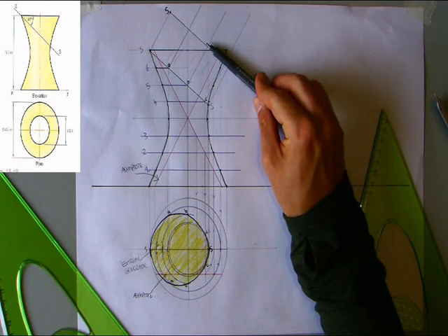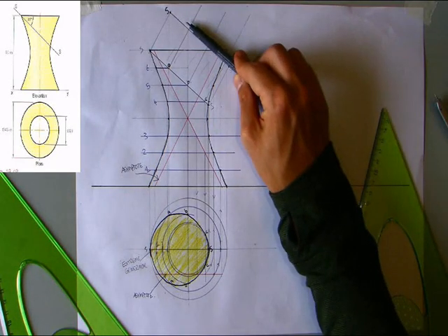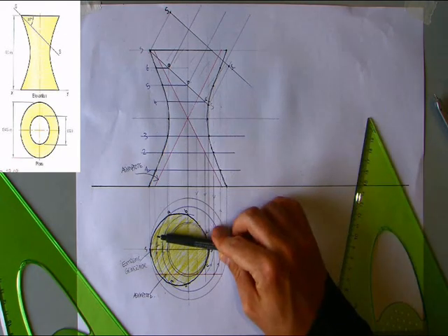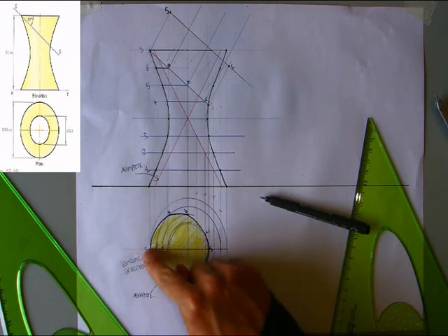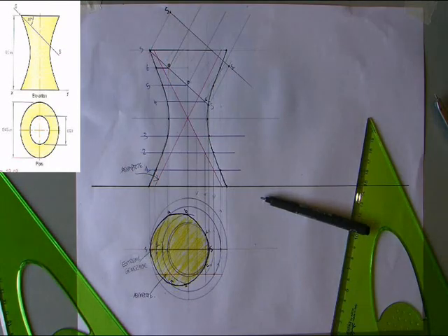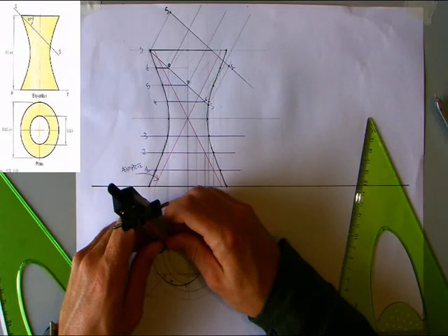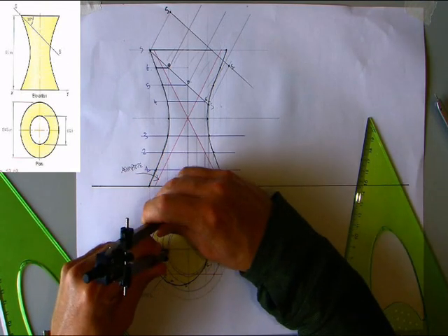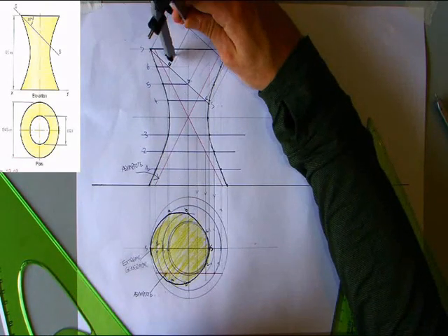So, to get our measurements for this true shape, we're going to go back 2 views, and that means this is an auxiliary view, so we're creating that drawing from here. That's back 1 view, and this is back our 2nd view, and all we're simply doing is, there's our major axis there, the line SS. We're going to take our measurements from A here with a compass and mark them off either side for our curve, okay, for our elliptical shape. So we do that using the compass. So from our symmetry line, or our extreme generator, we take the measurement of A and we mark it off.